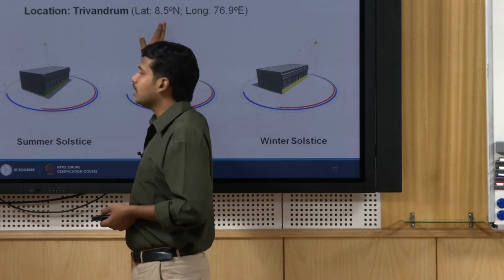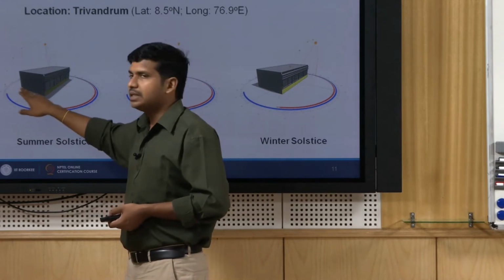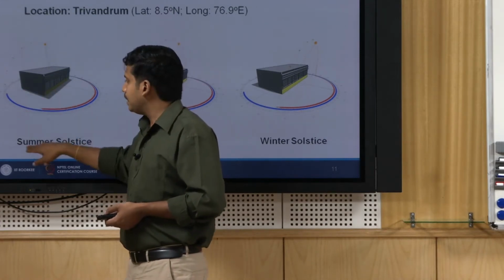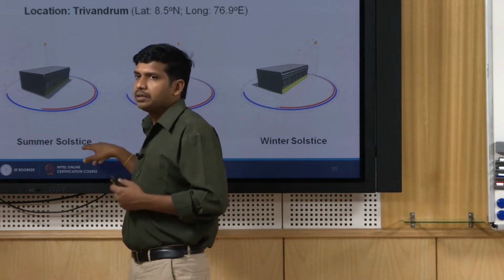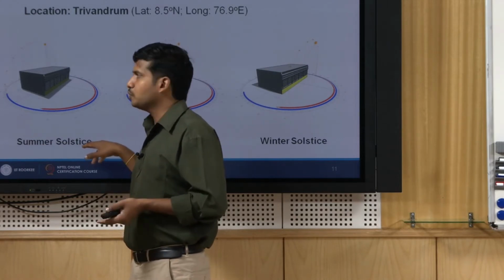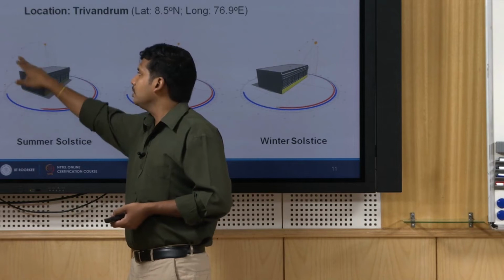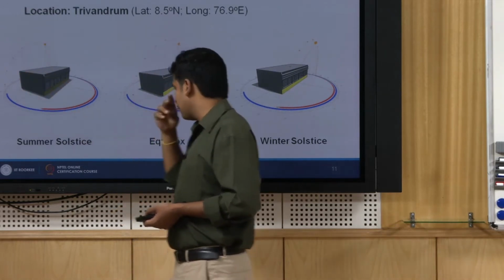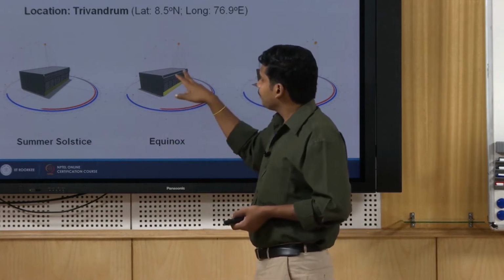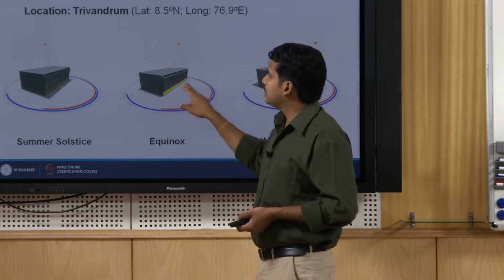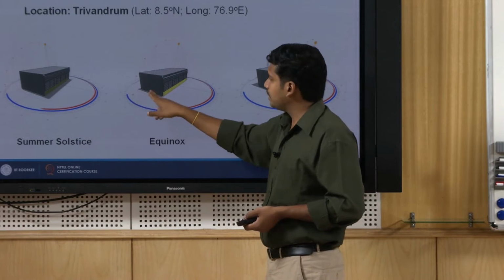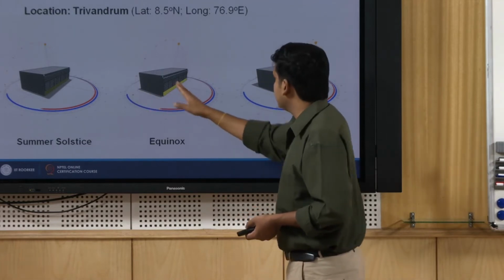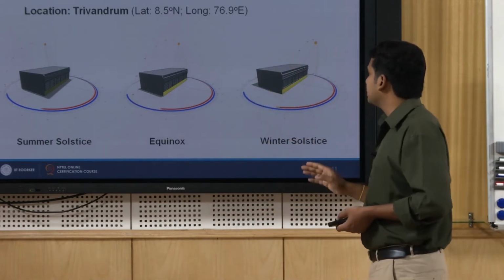You have to closely look at what latitude it is, because in critical months like May, June, July, when solar radiation is more and temperatures are also more, you are going to get direct solar radiation on your northern facade here. During equinox, east and west, a slight southern traverse is noted, it is slightly off the center point, traversing slightly towards the south.